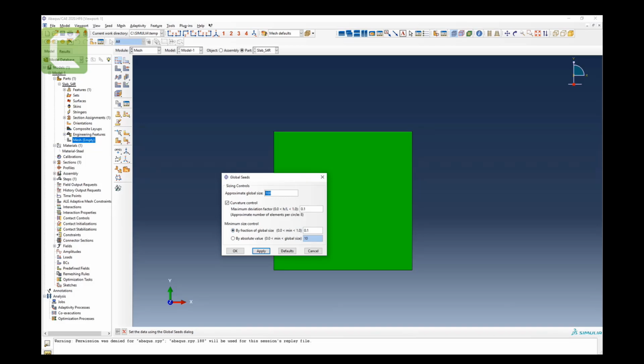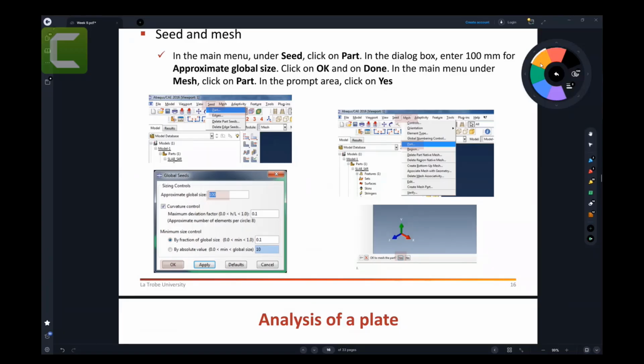But for example, let's say you have this kind of profile. And in this one, let's say you divide the mesh. The smaller the mesh, the closer you get to these surfaces, because these surfaces would become like this straight line, right? And there is a curved surface. So if you make a smaller mesh, it will give you more accurate results.